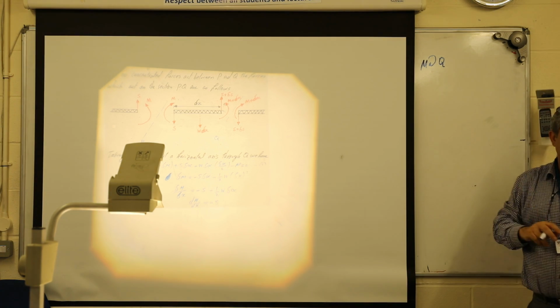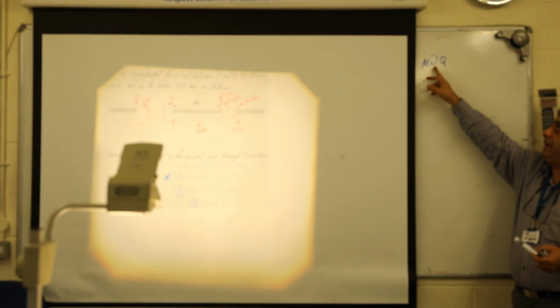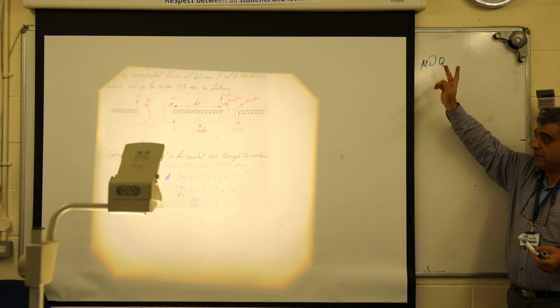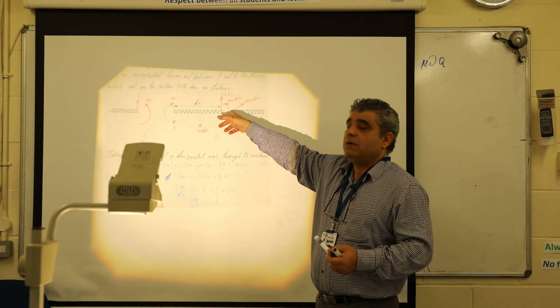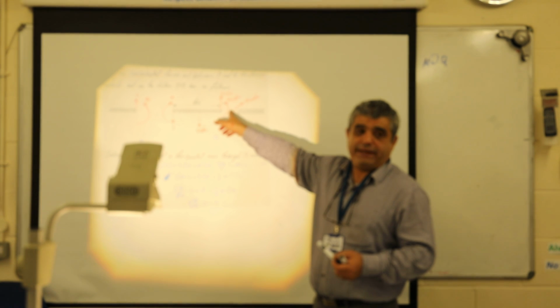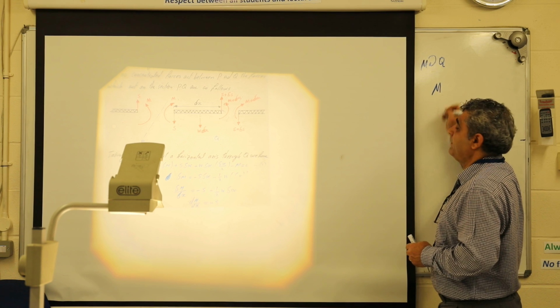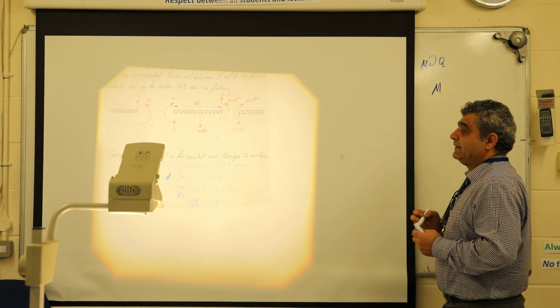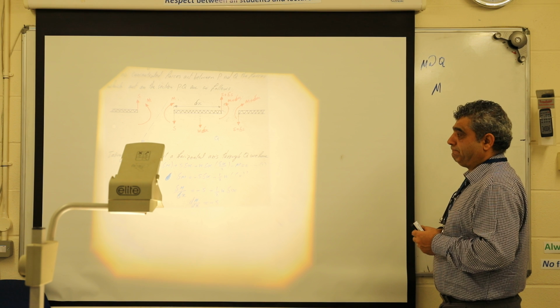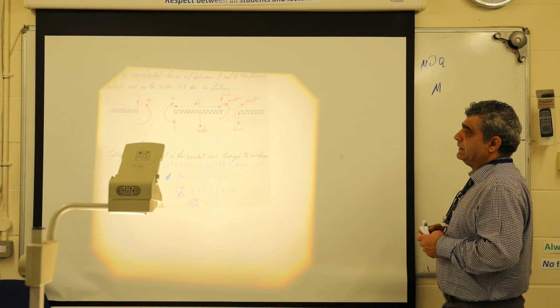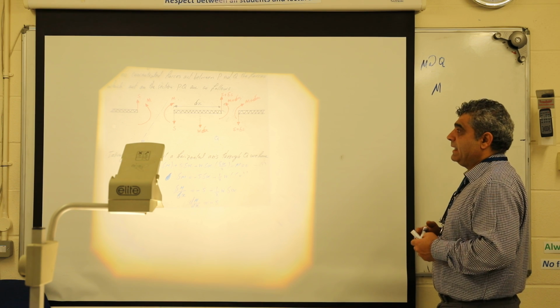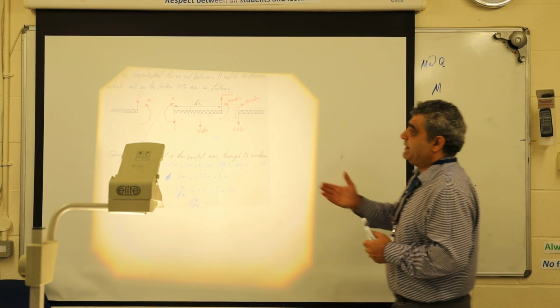That's the way we take the moment. You start like this, meaning you're telling me you want to take a moment about point Q. So put your finger at the point Q. When I do the cutting at the point Q, is there any moment occurring? Yes. So we can say M is a moment which occurs at that point. You can take it positive or negative, which we have here as well. Do you see that this M is already there?